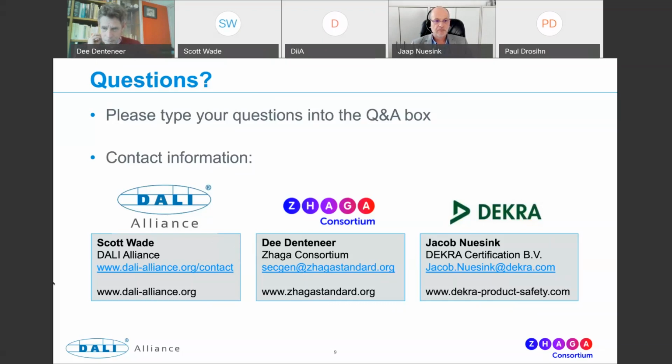All right, this is a question for Scott. My understanding is that DALI 2 drivers do not need parts 251, 252, 253. This is optional, but it is a requirement for D4i. Is there not a danger that a project mixing DALI 2 devices and D4i devices does not give consistent reporting?